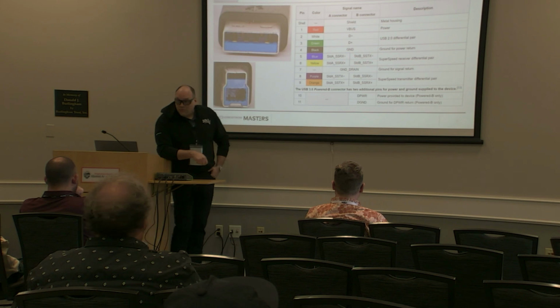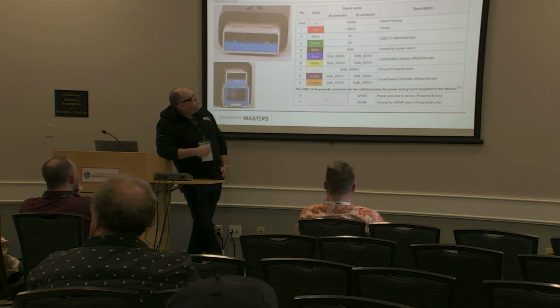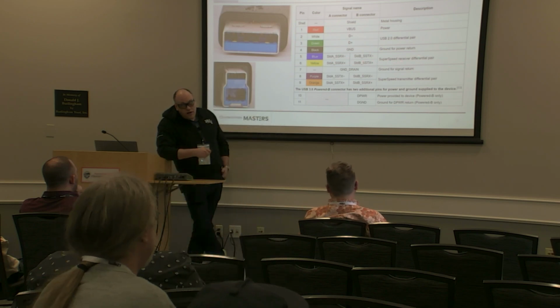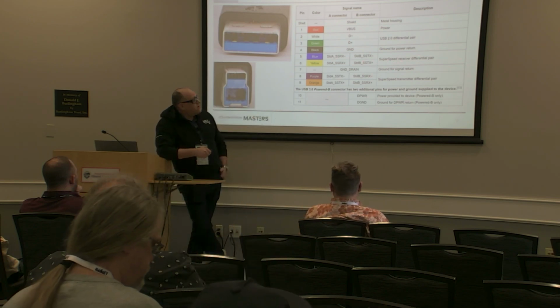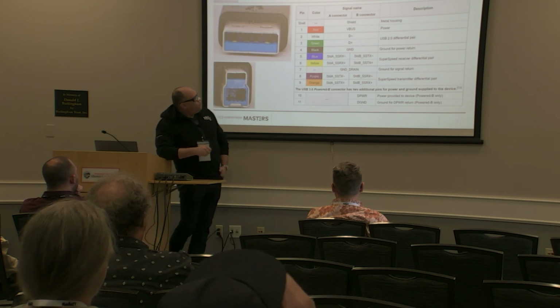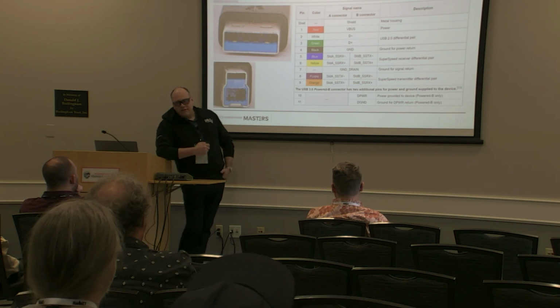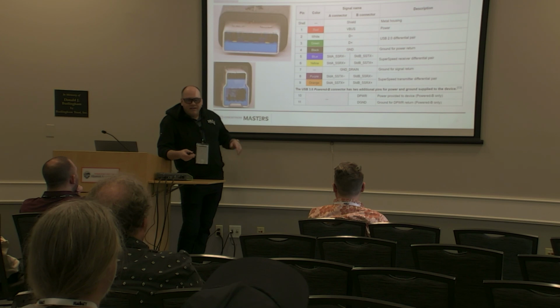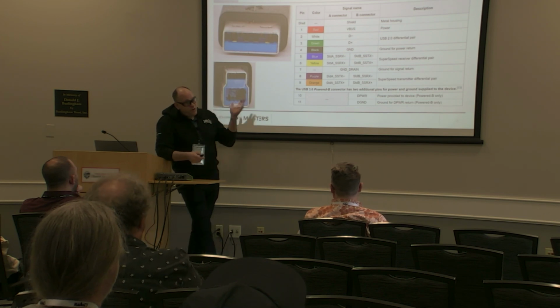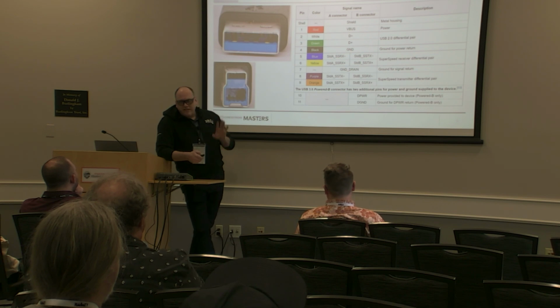What do we get with USB 3? How is it better? Well, we've added another 2 differential pairs, so a receiver and a transmitter. So this is how we get our high-speed data, right? And what, generally speaking, data rates are we talking about when we're talking about USB 3? There's 3.0, 3.1, 3.2. 40 megs? 40 megs? No. USB 2 is 480. We'll talk about that later, but I just want to briefly, again, that's kind of a gauge of where we're at with the room here.